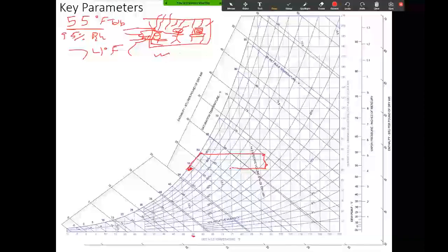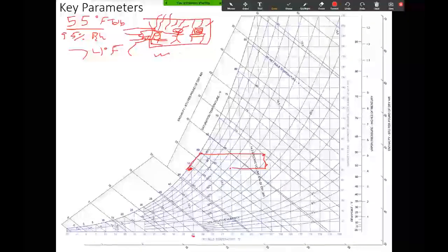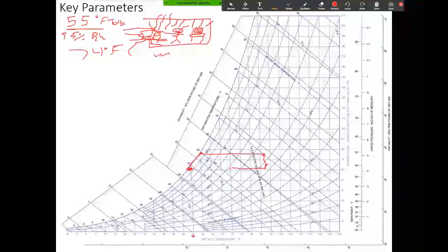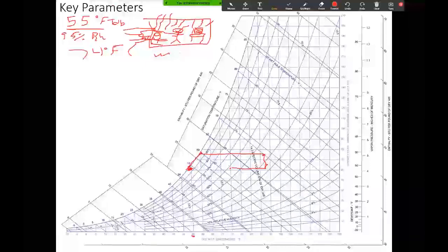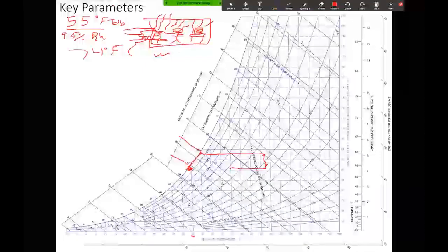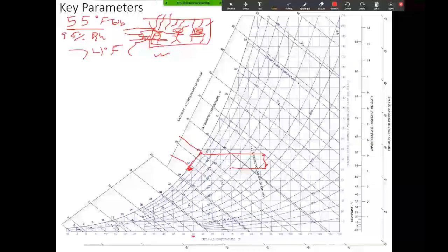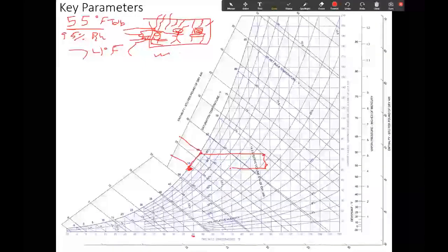Make sure I covered everything. Again, this relates back to the building as a system, and we can do calculations and figure out how much energy we need to remove to cool our air, or, if we're looking at the latent energy, how much energy we need to remove, right? If I have to go from 60 degrees on the dew point to 55 degrees on the dew point, I can say, how much energy do I have to take to get that temperature down per pound of dry air? What is this? 20, like 3 BTUs per pound of dry air, something like that. So this is bulk convective flow, and it's using bulk convective flow to add a cold air mass to the room, okay? And it cools down the warmer air that's already in the room. And this is how we control the relative humidity of the room.